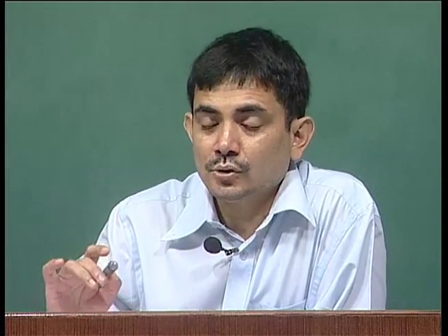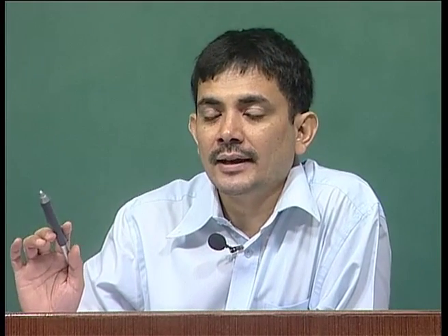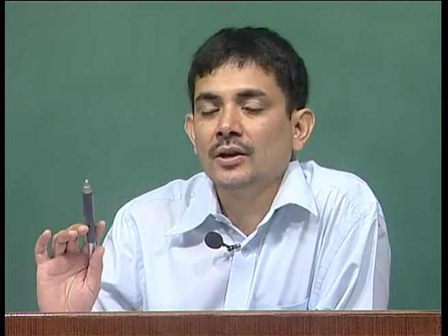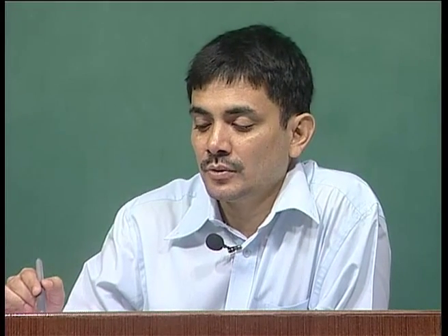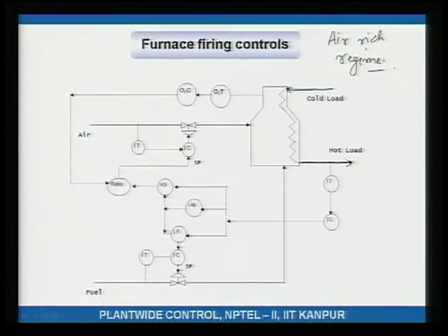To ensure that all of the fuel that has been put into the furnace gets consumed, you would always like to have sufficient supply of air. That means you would like to have always extra air, so that all of the fuel gets burnt and none remains behind inside the furnace. Okay. This is essentially a safety requirement.